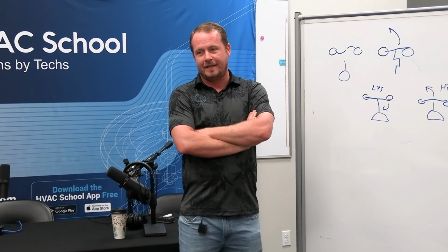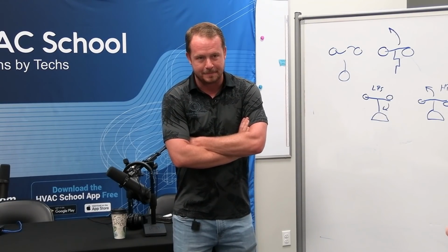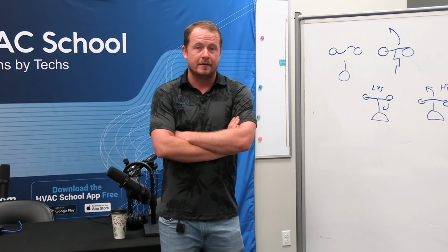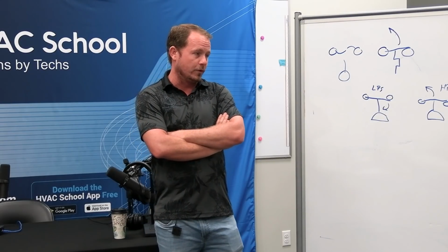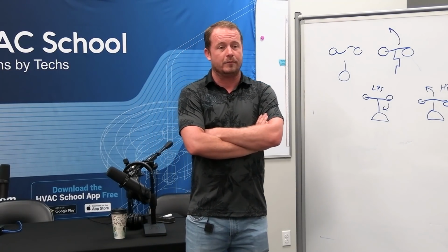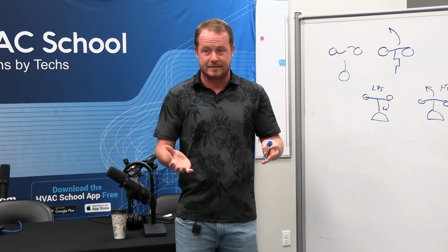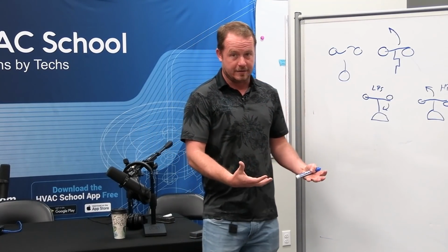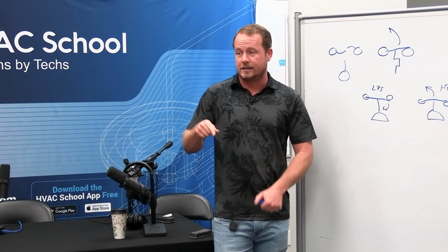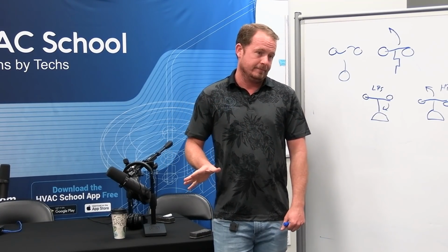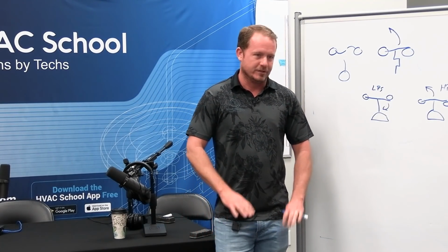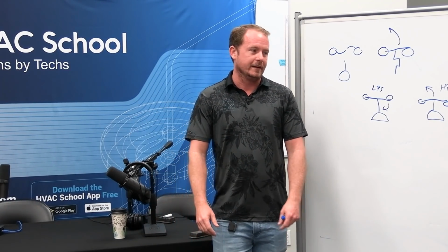All right, any questions about any of that? So the lesson is, if a switch opens, it opens for a reason. Figure out what caused it to open before you replace it. And also, with thermal overloads, it takes a lot longer with the compressor, especially because of the thermal mass, when there was a refrigerant reason for it to overheat. A lot of times it takes a lot longer for that to reset than you would ever think. But if you walked up and it was hot, it will reset. So don't do the whole thing, well, I guess it just won't reset. It will reset. So just keep letting it cool until it does.